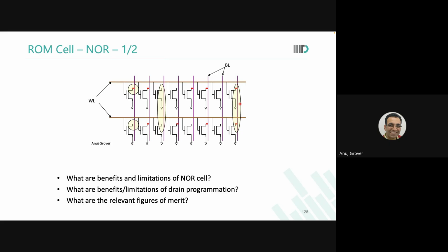But you anyways have to design for the worst case. So you have to keep the word line on for the worst case duration. The bitline will only discharge more. But the charge that you have to replenish is going to be the same. So no gain in power, but much more increase in complexity. Because now all these variables of what kind of coupling capacitance would come, what could be my worst case, all those things you're going to struggle with.